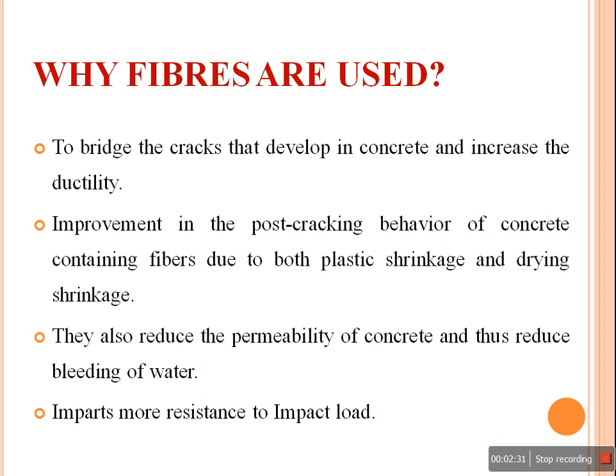They also reduce the permeability of concrete and hence decrease the water seepage into the concrete, so that any kind of water or liquid will not be stored in the microcracks that are developed in the concrete, and thus they reduce the bleeding of water and further damage to the cracks already formed in the concrete. And they impart more resistance to impact load. Not only impact load, they even increase the tensile strength capacity of the concrete and compressive strength also.